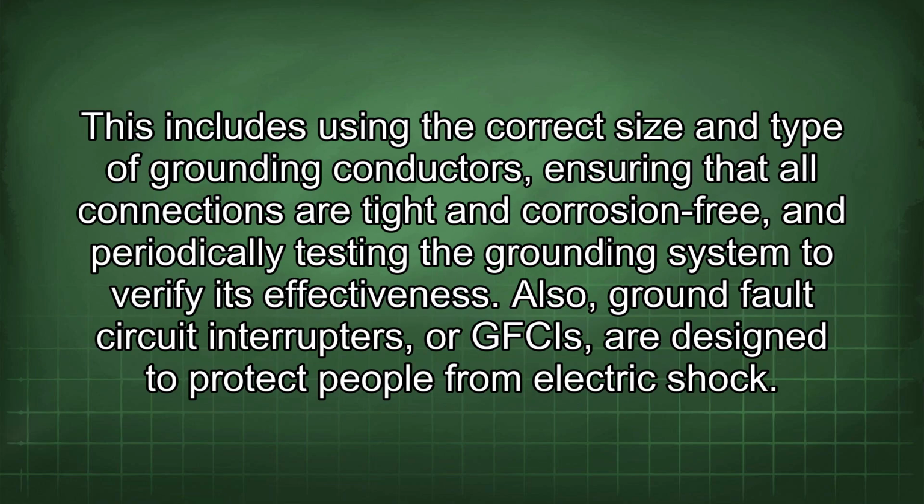This includes using the correct size and type of grounding conductors, ensuring that all connections are tight and corrosion-free, and periodically testing the grounding system to verify its effectiveness.